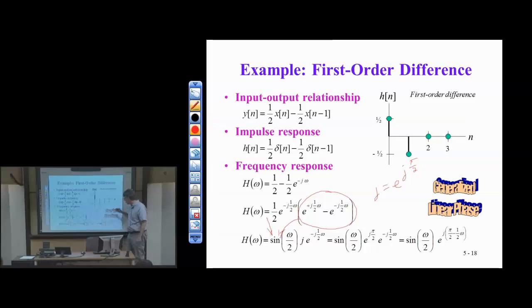So I can at least get it in the same form as my phase. This is called generalized linear phase. This is a phase response that does not go through the origin, but is a line. If we apply the group delay definition, which is to take the derivative of the phase, this constant goes away when I take the derivative with respect to omega. It doesn't affect our group delay. The group delay remains 1/2 sample. So that's 2.1 on homework, parts A and B.